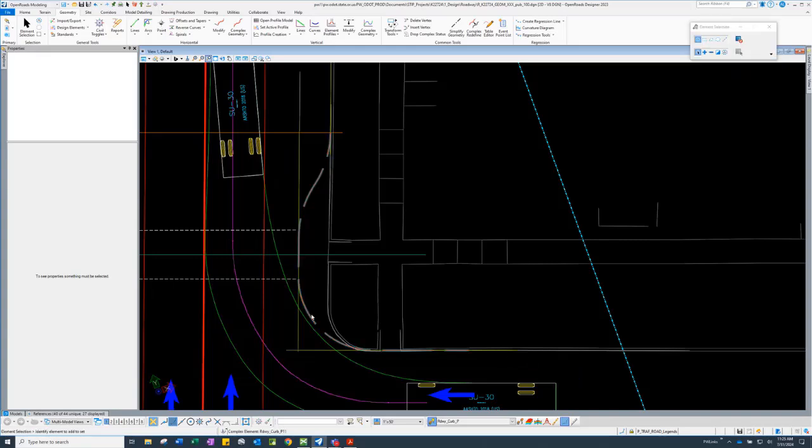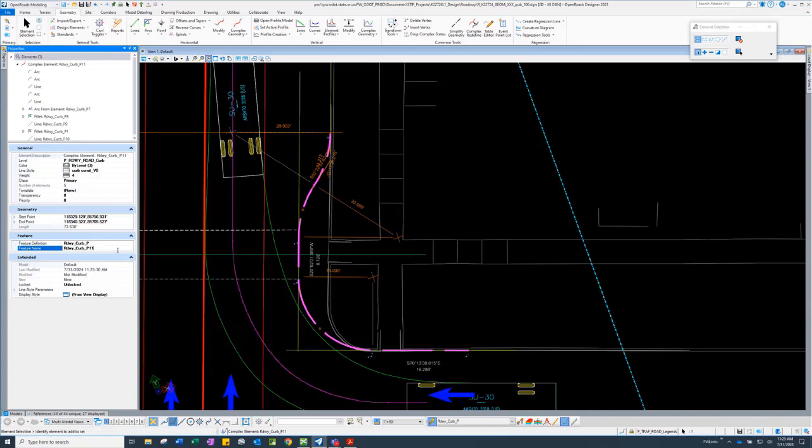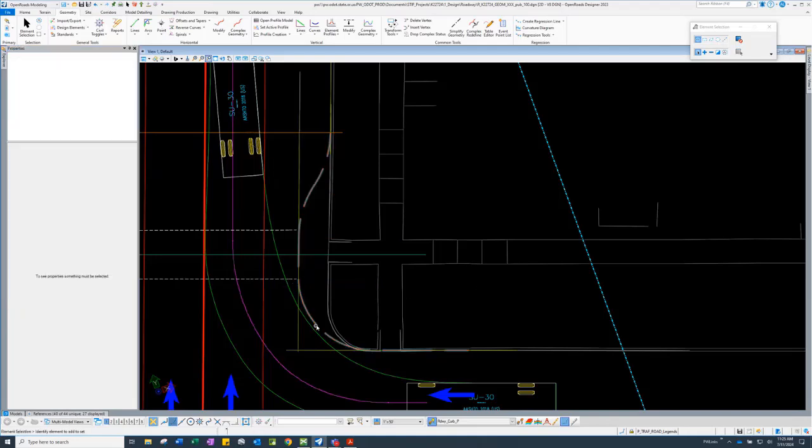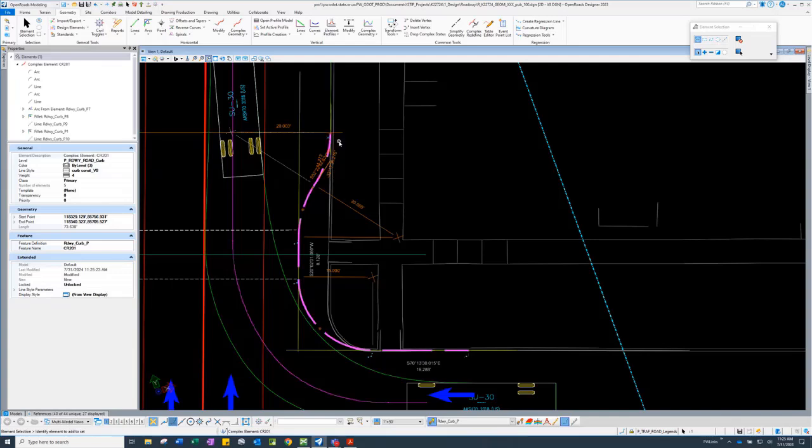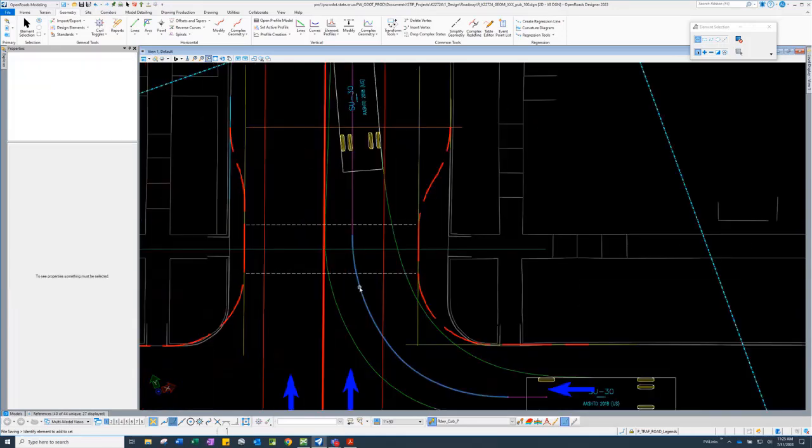So now I have curb. I can now rename it 201 because the other side's 101. That I can assign a station to. I can label. I can display annotation for plan sheets. And then I can also model from. So that's the start of this layout, right?